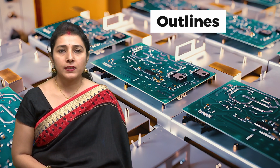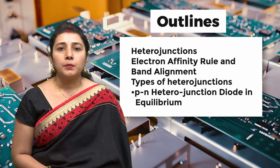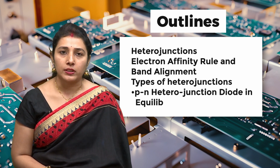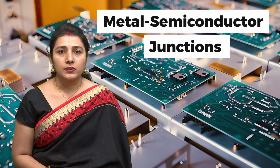We will also discuss heterojunctions, electron affinity rules and band alignment, types of heterojunctions, and the p-n heterojunction diode in equilibrium condition. So, let's start with metal semiconductor junctions.